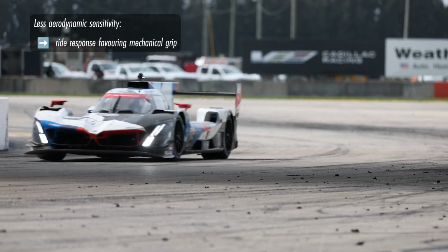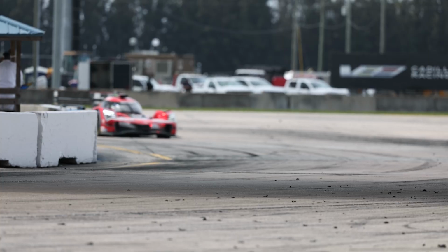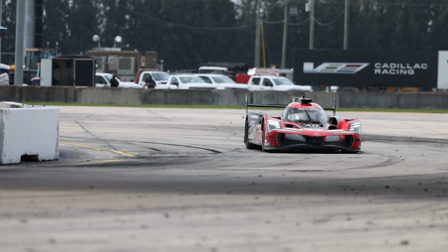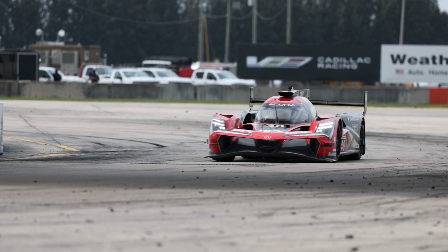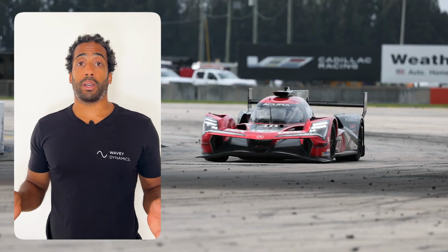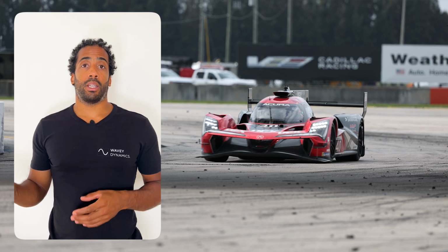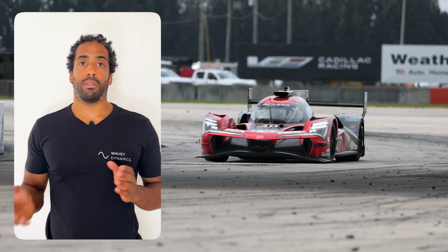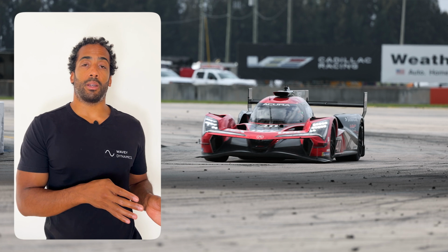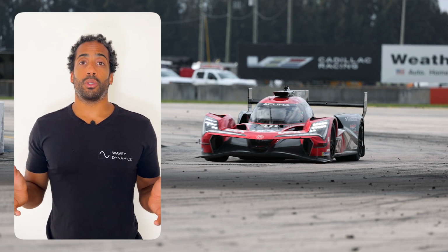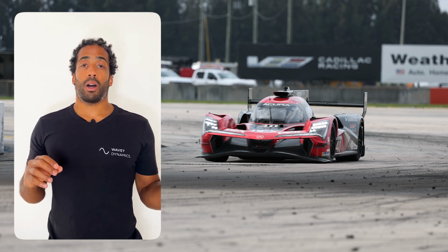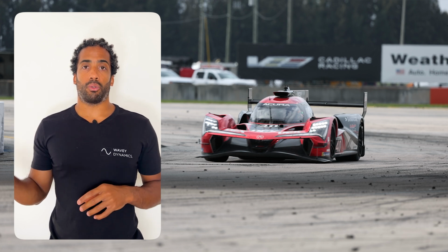Because of the much higher spring stiffnesses and the higher damping rates, there's going to be a lot more variation in the vertical loads between the contact patch and the track surface. Okay, so how can I see that? The variation in the load which the contact patch is seeing is very strongly linked to the natural frequency. So let's take two vehicles of the same weight.